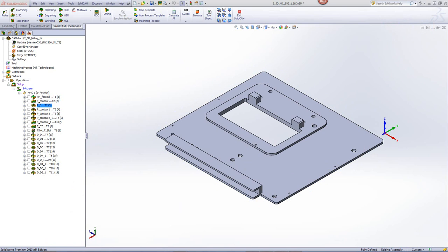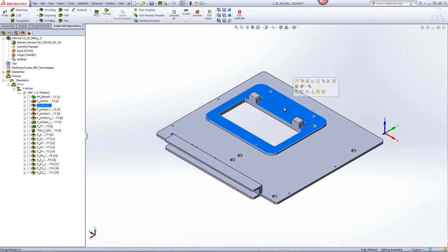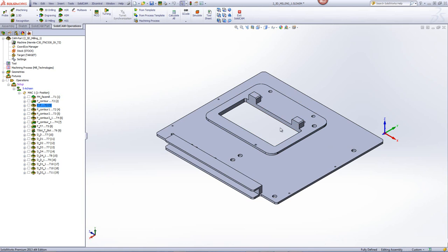Now we'll look at the island and pocket machining done on this part itself. The islands in this particular case, the first case is talking about this floor over here, this being an island inside that area over here. We're using a pocket operation for that, as well as this floor over here being open on all sides, and these 2 nubs acting as an island. The third operation is just a regular pocket operation over here, cleaning out this entire pocket.